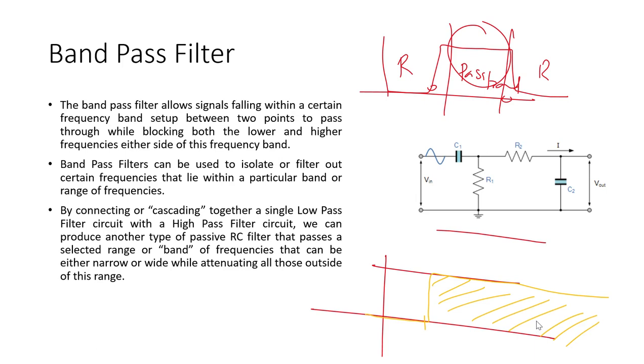After that, we will introduce a low pass filter with it. So what will the low pass filter do? The low pass filter will delete the higher band that is not required. So let's say this is a low pass filter and this band is deleted, this is not required, and we are left with only this band now.